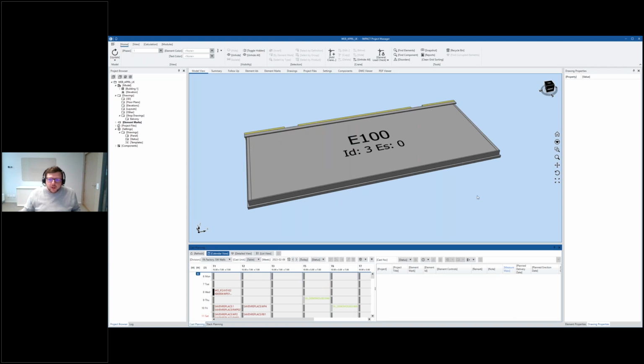So of course, this was a simple balcony. You can have more complex shapes and so on, but it's pretty much the same steps that you need to do. A good idea is to create a polyline of the geometry and draw the slab according to that polyline. Then you get it automatically.